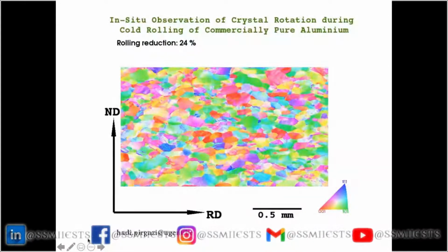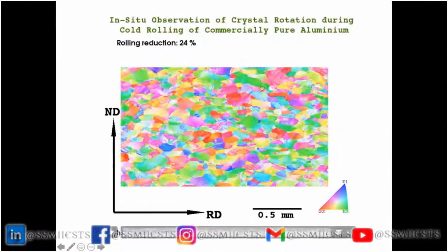Not only that, there is a second important thing that you can observe, that is that there is a gradient of colors appearing. Originally, all these grains had more or less a uniform color, a uniform crystal orientation. And after some while, you see that there is an internal grain gradient. So this means that the orientation splits up, in fact. It's not a homogeneous orientation anymore.